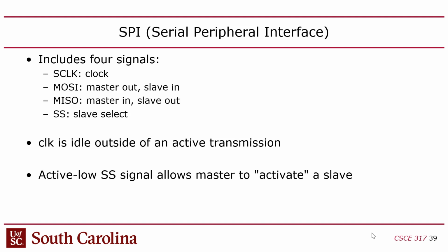But in a synchronous communication channel, you can have the clock run only when you're actively communicating. Whenever there's no communication happening on a channel, the clock is idle, meaning it's just flatlined. This is something unique to communication channels as opposed to digital logic designs. In a digital logic design, your clock goes forever. As long as the chip is powered up, generally you're going to have a clock signal.